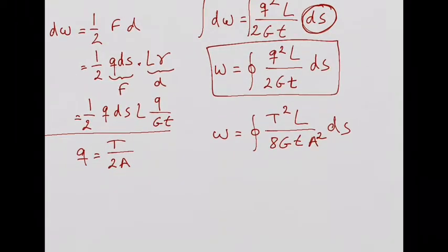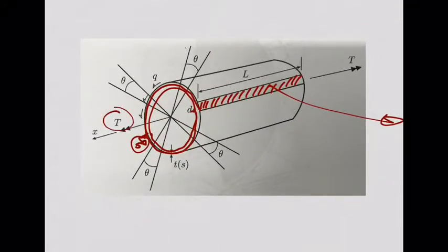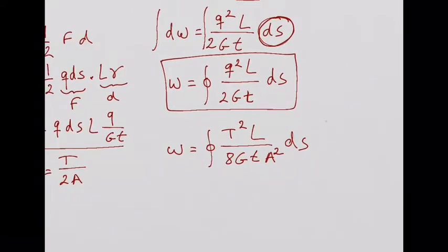So another thing, we also can keep this expression, because one important thing is that you have the torque squared, but the torque in the cross-section is constant, so we apply a constant torque in the cross-section, right? So basically we can send the torque outside of the integral. We can send torque, we can send G, we can send A, these three guys outside, right?